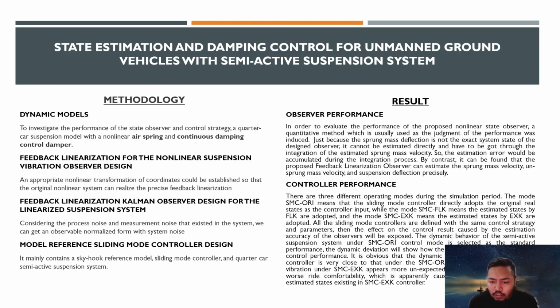From the controller performance, there are 3 different operating modes during the simulation period. First is SMC ORI, second is SMC FLK, and lastly SMC ESK. It is obvious that the dynamic response under the SMC FLK controller is very close to that under the SMC ORI controller, while the vertical vibration under SMC ESK shows unexpectedly larger peak values, meaning worse ride comfort, which is apparently caused by the distortion of the estimated states in the SMC ESK controller.